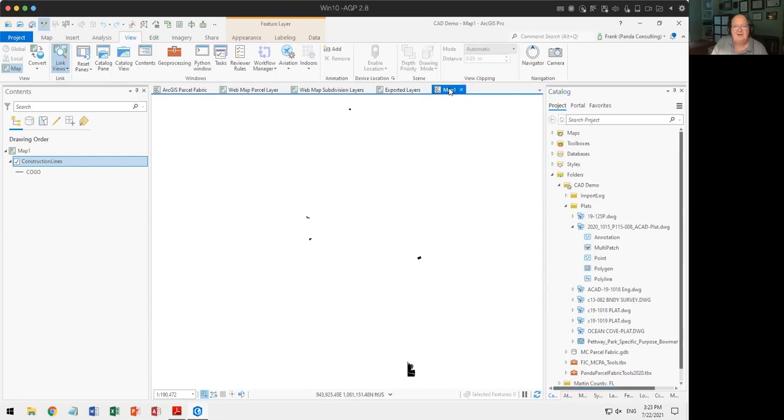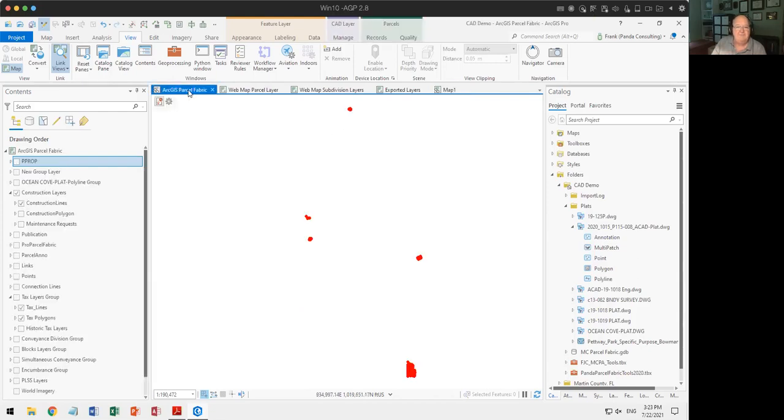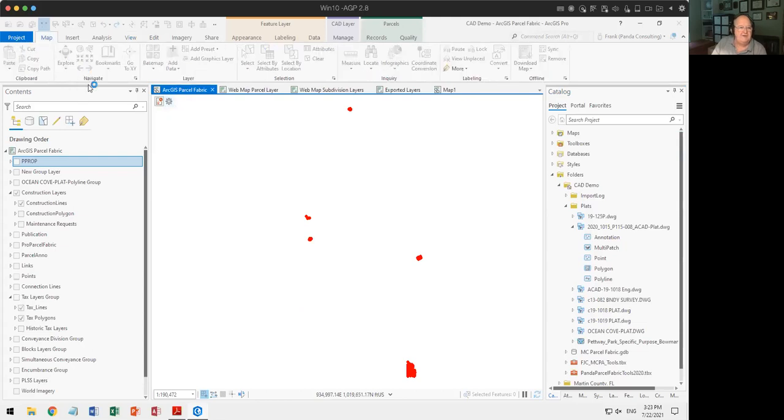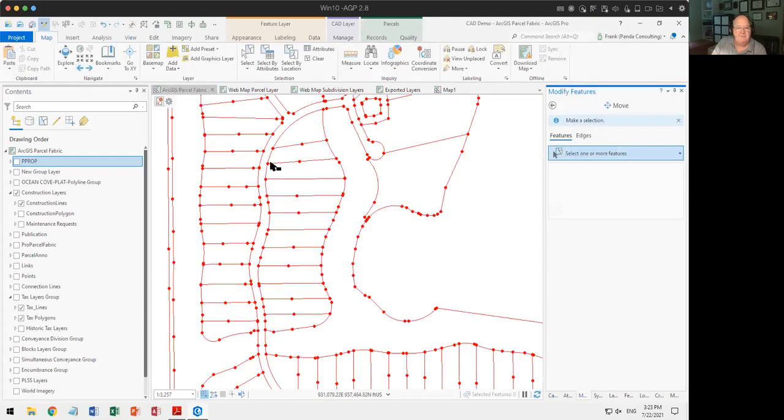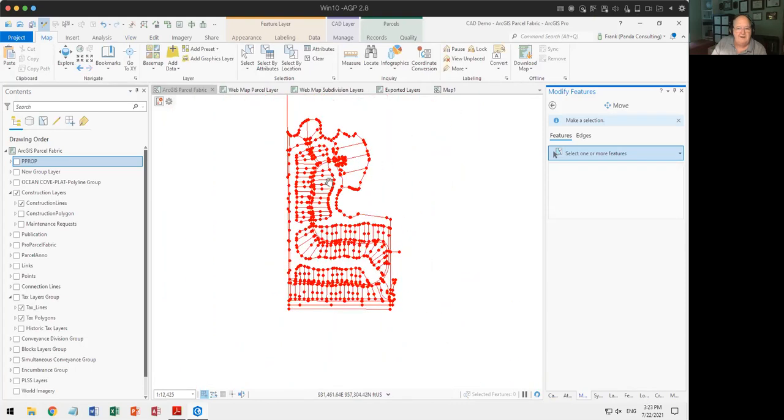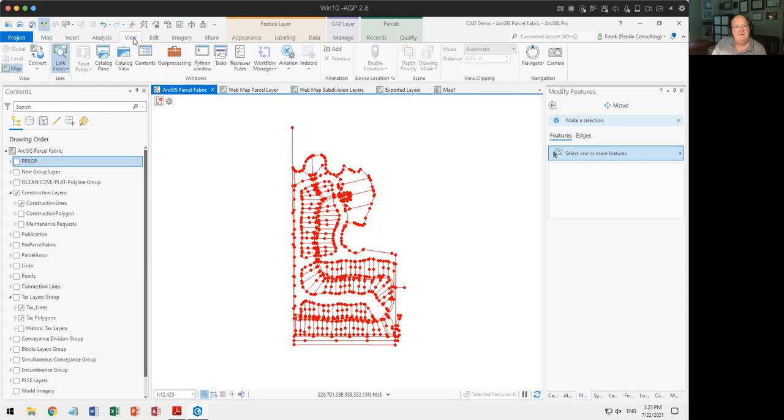It gives me a chance to show you some other elements of ArcGIS Pro. For example, I've created a new map inside of this project file, but it doesn't coordinate with any others that I have. So I'm going to go back to this main one that I had, and go to my last view here. Then there's a tool under the View tab that says, take all of my maps and keep them synchronized as far as the scale and centering, so I can do that.